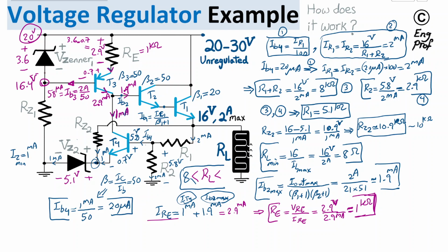In practical design, if we support a current of 58 microamp, let's say 10 times that, which is 5.8 milliamp. So if I set the current going this way 100 times more than 58, meaning at least 5.8 milliamp current through RZ1, then as a result we can neglect the impact of this, and we can say the current through RZ1 is fixed, say even at 6 milliamp.